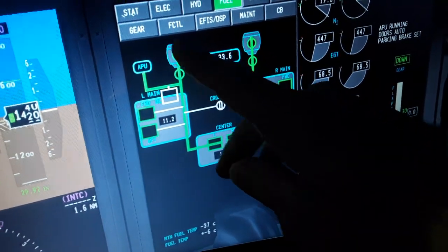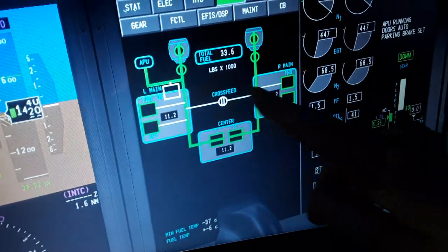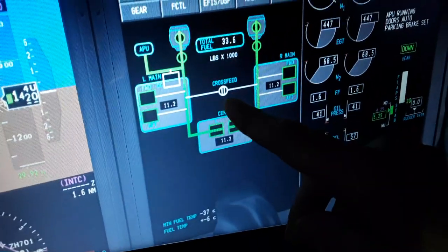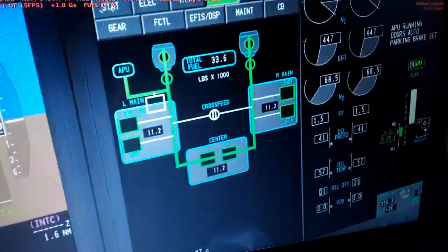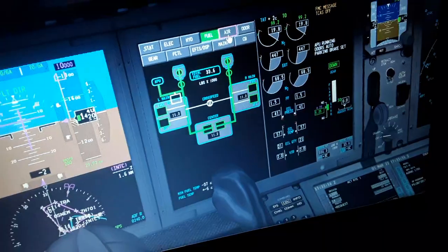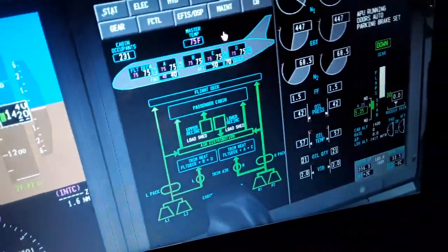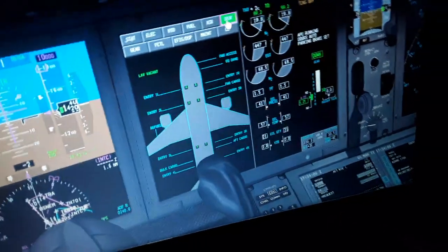So we have the low and high pressure fuel valves open and feed both engines. The cross-feed valve will automatically feed either engine with either pump. Also the EPU is fed from the left wing using this motor. Also the recirculation of fuel also recirculates the lubricant and the oils for defreezing. We have the pressure for cabin pressurization from the engines and the EPU, oxygen, other systems.